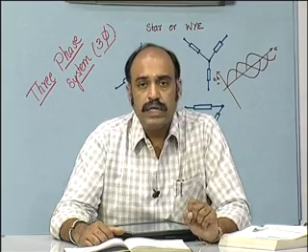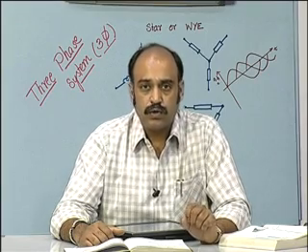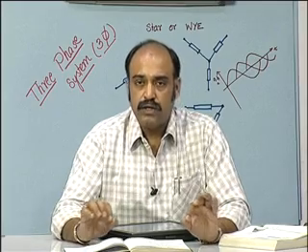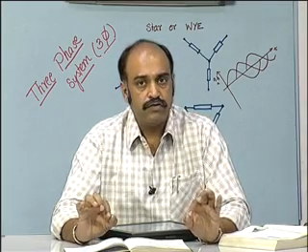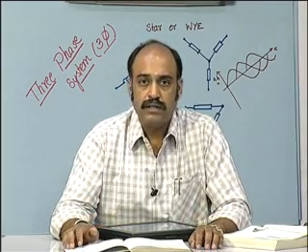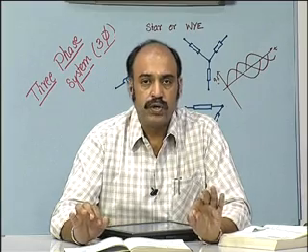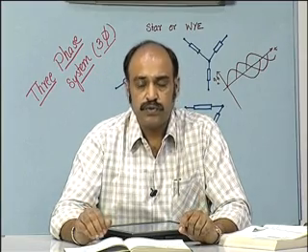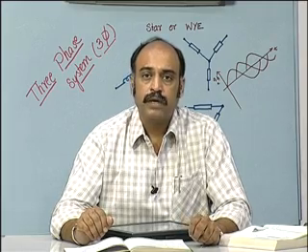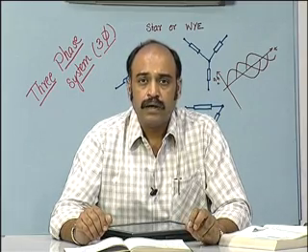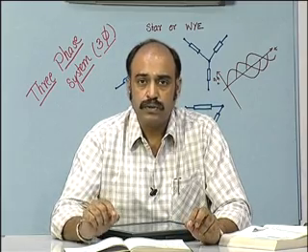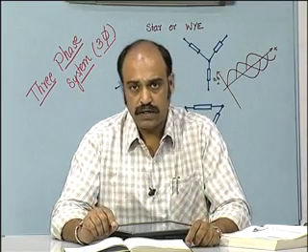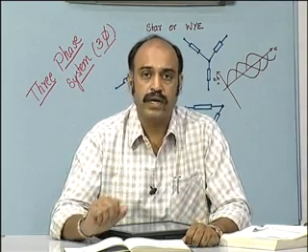The neutral point in star circuits plays an important role: if the loads are balanced, the neutral points can be left floating, because under balanced load condition IA plus IB plus IC is equal to 0, which we saw and discussed in the previous classes. Therefore, there is no need to connect the neutral point of the load to the neutral point of the source. There need not be a return path wire.